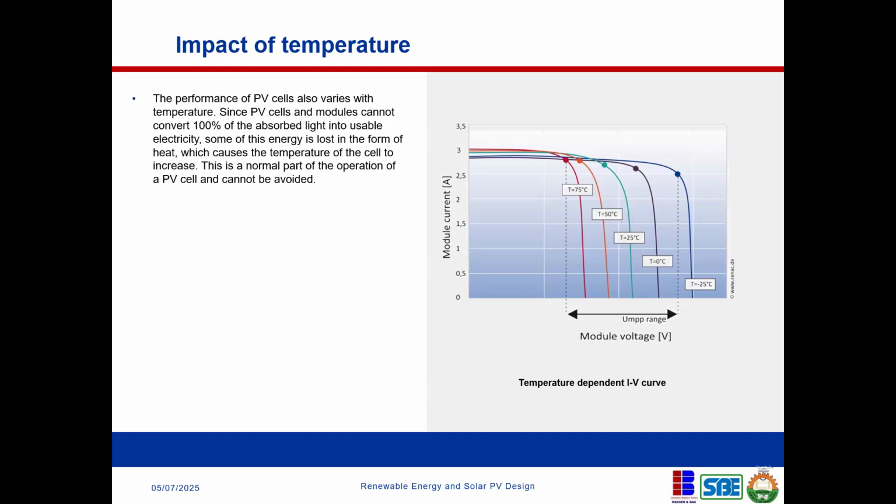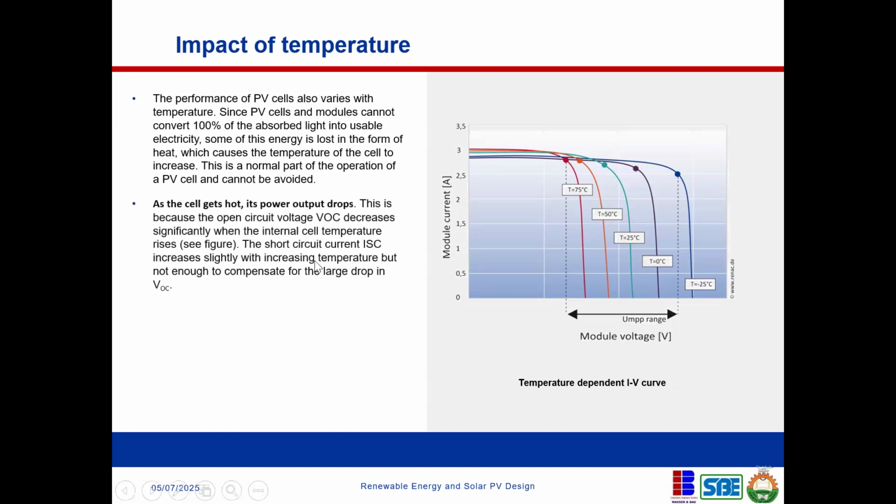And then during the harmattan, during the dry season, during the hot weather, even when the sun is at optimum, it's very high, and the weather is hot. The intensity is high, but that intensity also comes with a higher temperature. So that higher temperature will reduce the output of your module. Okay, so you will not have the same yield as you would have had during the cold, rainy weather period. I'm just saying this so you can understand the impact of temperature on the yield of solar panels. So this is how temperature affects the yield of your solar panel.